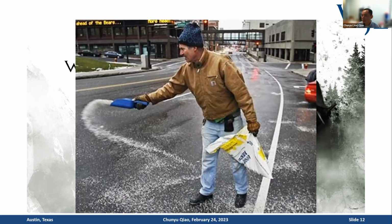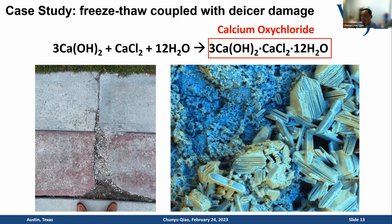So what do we do when we have a lot of snow in the winter on the road? We still want people to drive, we want people to walk on the sidewalk. So we remove the snow and we apply a lot of de-icers. De-icer is very good to keep the traffic open, but de-icers can be really bad, damaging to concrete. This picture on the left is just a regular sidewalk I took outside my hotel in Chicago. It's a sidewalk with a lot of de-icer. After years, you see this kind of very premature joint damage.